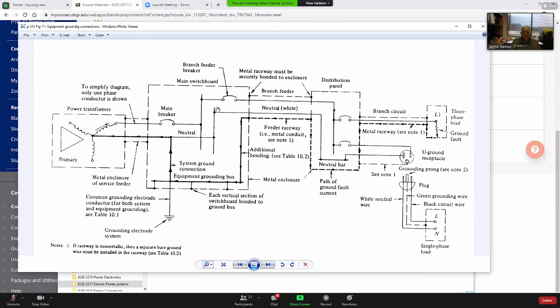Or no, there are two breakers, three breakers. So we must have coordination of breakers. We do not want the breaker on the main switchboard to open, nor the breaker on the distribution. We want the breaker on the distribution panel to open, the one to the right, because of the coordination of breakers. Fine. So then I'm going to stop here, but before we go, I want to show you something else.